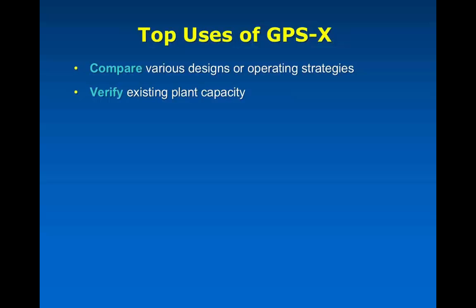And when you get to that failure point, you can actually look into the details of how it failed. Where is that bottleneck? Is it because I don't have enough oxygen? Is it because I don't have enough clarifier capacity? Am I running out of digester capacity? That sort of thing. It allows you not just to understand that the plant will fail at a certain flow rate, but to understand which part of the plant is the weakest link.